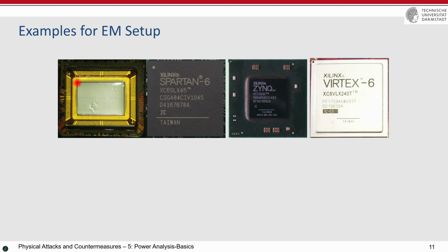And this is one technology, that you have the chip which is fabricated. This is the semiconductor, but because it's super tiny and this example is super large. I mean, the chips that, for example, I design in my group, they are 1 millimeter by 1 millimeter in size. But at every side, at every millimeter, we have 12 pins to be connected. And then there should be bonding wires that connect this to the package, which is, of course, much larger, let's say 3 centimeters by 3 centimeters. This is the size. This is one technology, with the bonding wires.